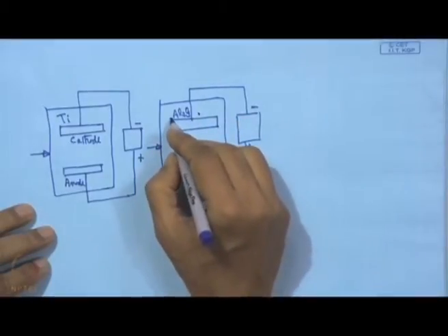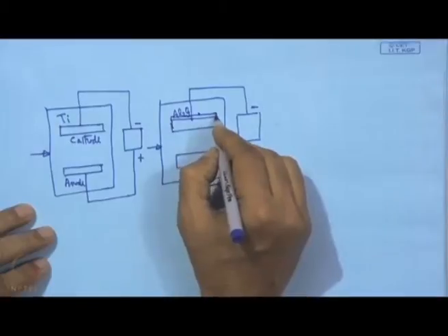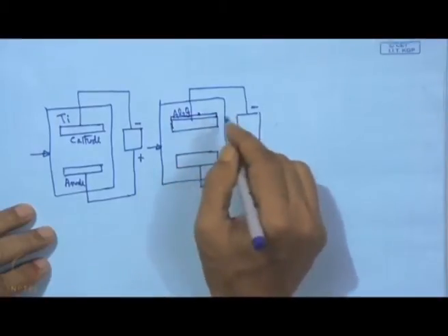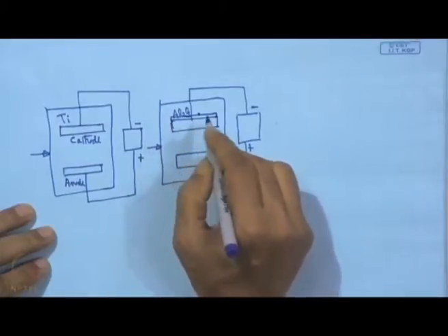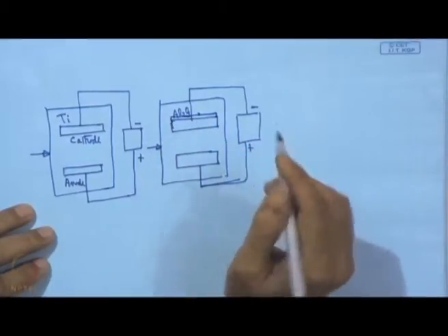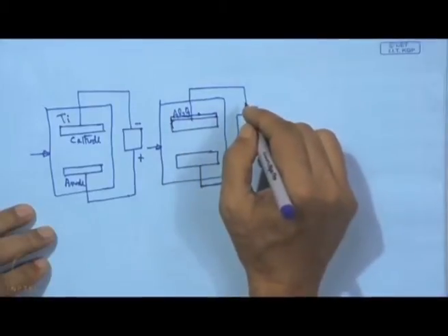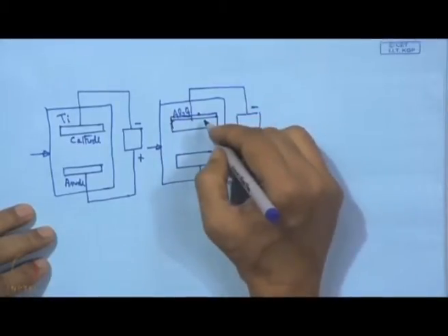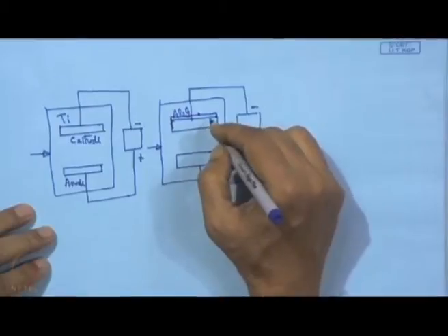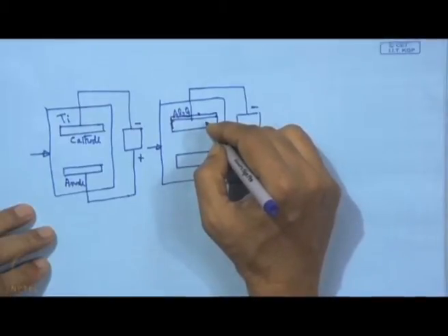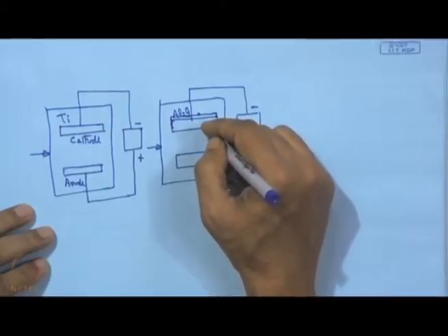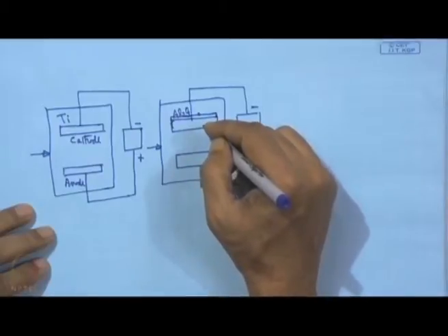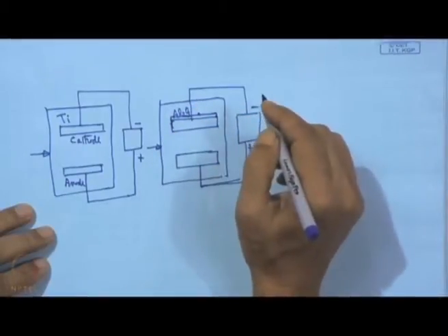Though we have a cathode plate just behind it, on top of it we have a target material which is a non-conductor. So, there will be accumulation of charge, and it will ultimately lead to heating of the target, and it can even lead to arc discharge, which is the most undesirable thing in this whole sputtering process.